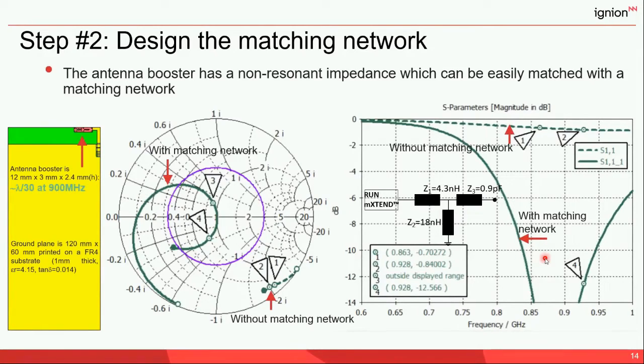And this is very flexible because you can do it at any time of the design process. Perhaps you are very close to certification and you are adding a new material on the device, like some plastic covers, and the antenna system gets detuned. You don't need to design a new antenna. You don't have a bottleneck on the antenna. The only thing is to retune the matching network, and again you have a good response, and you are sure to have your device certified.